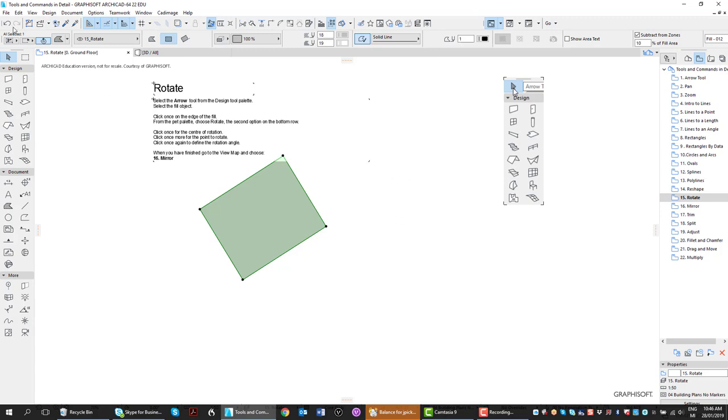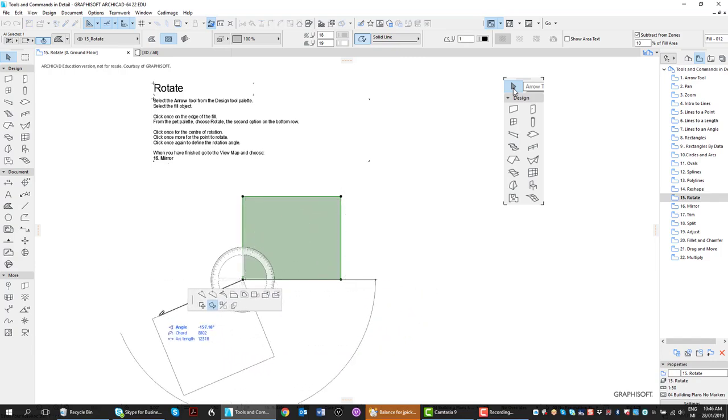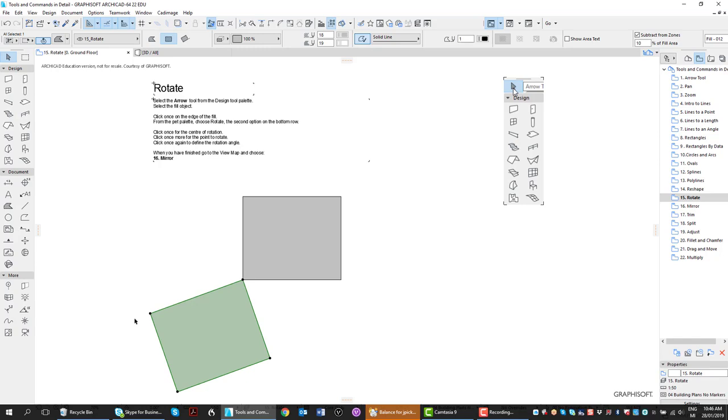I'm just going to undo that. Let's do that again. So click, we're going to rotate. So you notice it's already selected rotate. Click, click. This time I'm going to go the other way. But just before I finish, I'm going to hit the Control key just once. And you'll see a plus turn up next to my cursor. When I click, it duplicates my object.